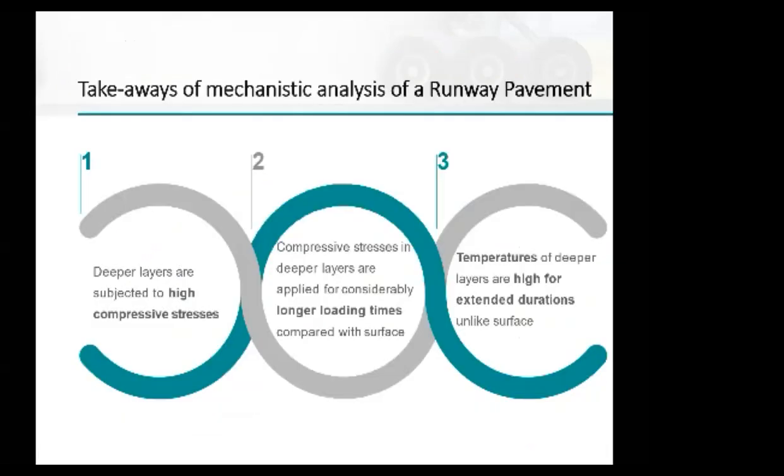What the results told us are the following 3 things that I would like you to take away from this presentation. 1, deeper layers are subjected to high compressive stresses. When you go deep, compressive stresses in airfield pavements are still very high. 2, compressive stresses in the deeper layers are applied for considerably longer loading times compared with the surface. So this intermediate layer and base layer are feeling high stresses, but not only that, these stresses are lasting for a long, long time.